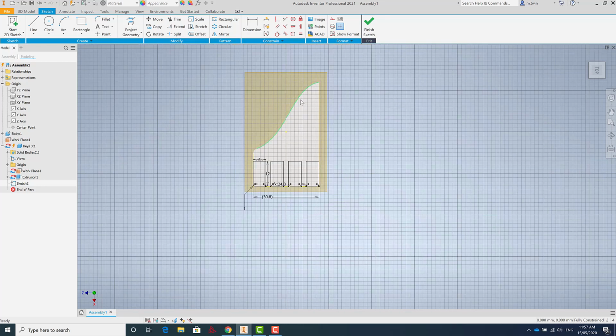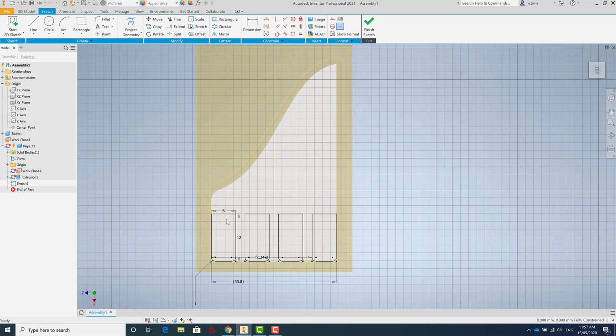Excellent. Now all these keys are based on that first dimension, and it looks like they're a little bit too deep here to really get a decent amount of vibration on that first key. So if we come in here and we change that down to say 6 millimeters, because I really do need some room there, it changes the dimensions of all the keys. Great. So we've now got a decent amount of room here to create a little tab.